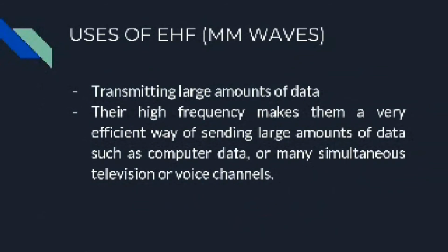Every kind of wireless communication, such as the radio, cell phone, or satellite, uses a specific range of wavelengths or frequencies. Each application provider, such as a local television or radio broadcaster, has a unique channel assignment so that they can all communicate at the same time without interfering with each other. These channels are bandwidths, also measured in either wavelength or frequency, that must be large enough to pass information from the broadcaster's transmitter to the user. For example, a telephone conversation requires only about 6 kHz of bandwidth, while a TV broadcast, which carries much larger amounts of information, requires about 6 MHz.